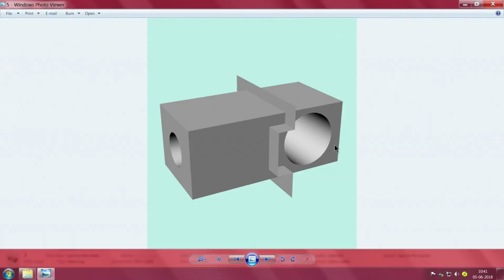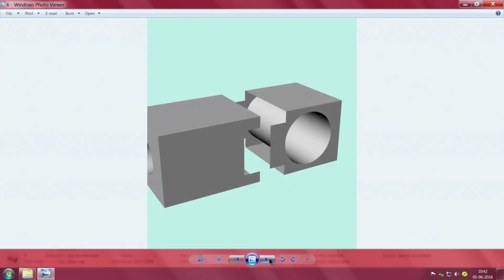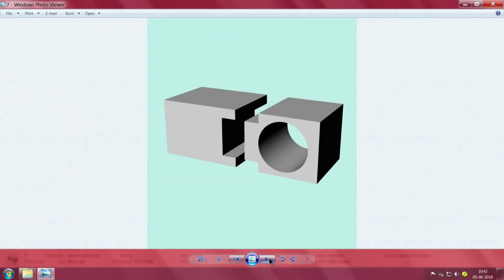So what has been suggested is you cut it into two parts. This is what I was trying to tell you yesterday, or rather the previous session. Now you see here I have made a hat-section-like thing such that I split the object into two parts. After splitting it, this part can be built with this face down, and this part will be built with this face down. So we have no necessity for any build material to be coming inside. If you see here, it has been cut in this place and we have this. Easy, is it not?